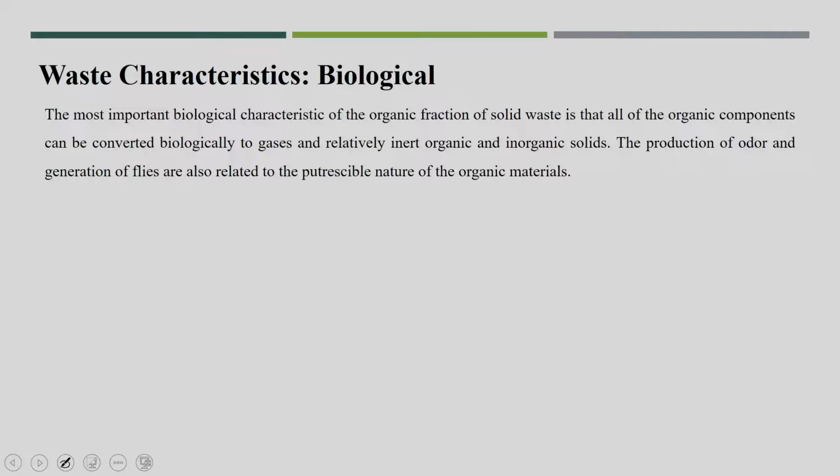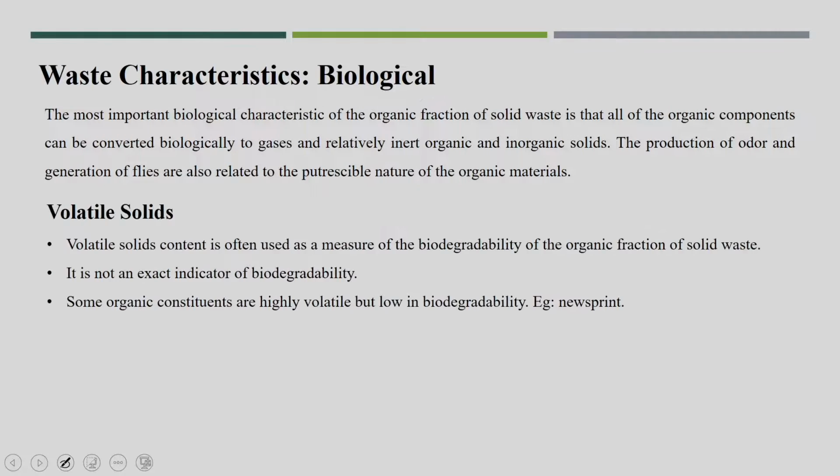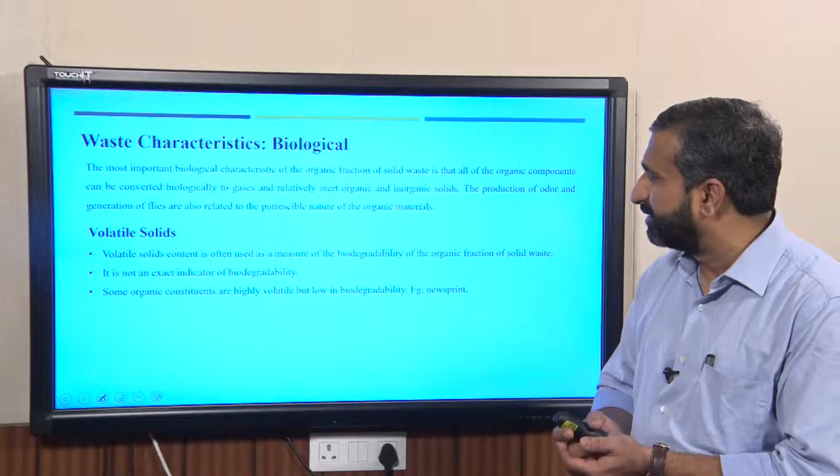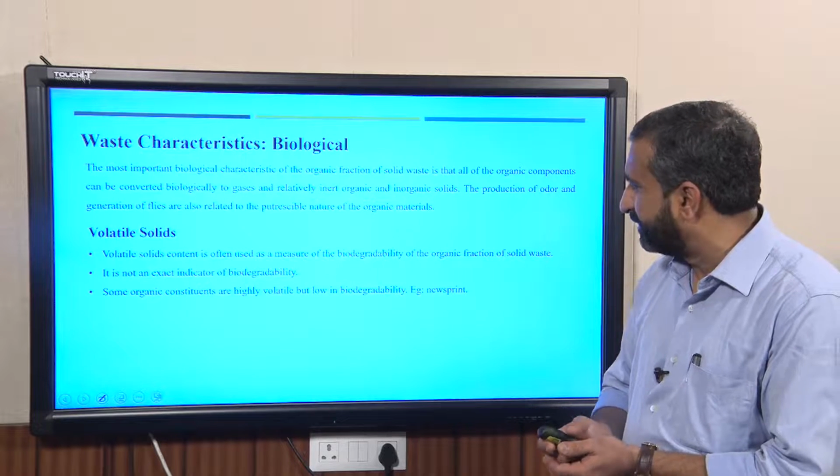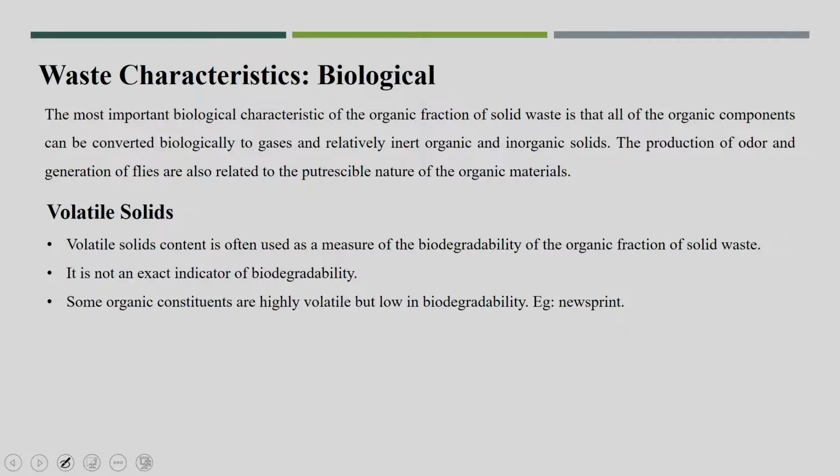Now, the biological characteristic is one of the very important characteristics, to know the biodegradable fraction of the solid waste. This we normally do by volatile solids, the same way we analyze the solid waste for volatile content. This is not the exact indicator of biodegradability, but if you know the volatile quantity, for both the incineration facility and the biological treatment facility, this parameter is very important.